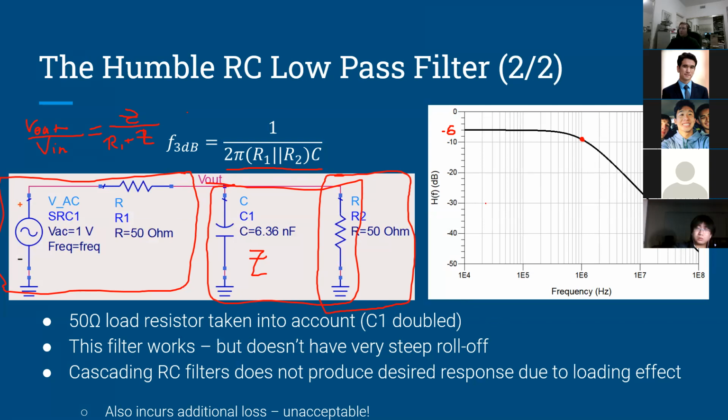All right, so the 6 dB here is to be expected. Regardless of what type of filter we use, we're always going to get a 6 dB loss from input to output because we have that voltage division. So that's nothing to worry about. When you typically look at filter responses, though, you usually ignore the source resistance, and you kind of shift this curve up to 0 dB, and ignore whatever voltage division you're seeing.